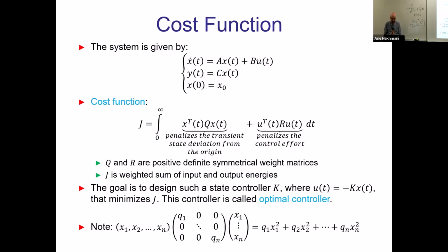But now, practically speaking, we converted one problem into another problem. Technically, this is how optimal control works. Have we really solved the problem? Because the previous problem was where do you put the poles? Now we do not have that problem. We will put poles wherever they are to minimize that thing. But in that case, we need to choose what R and Q are, which means we had one problem, where to put the poles. Now we have a problem of what Q and R you need to choose.